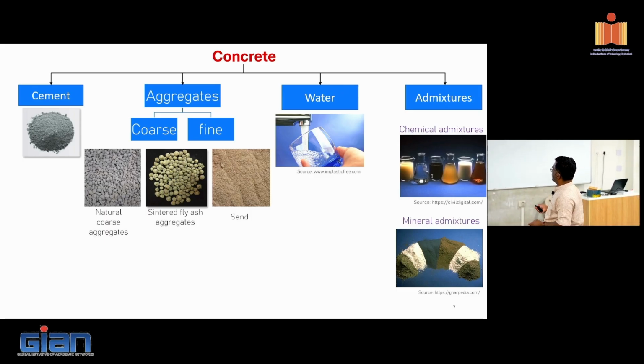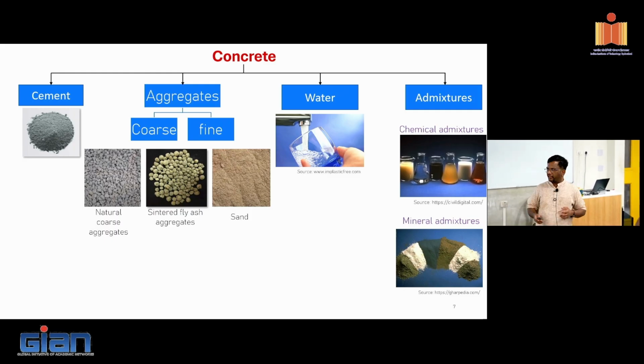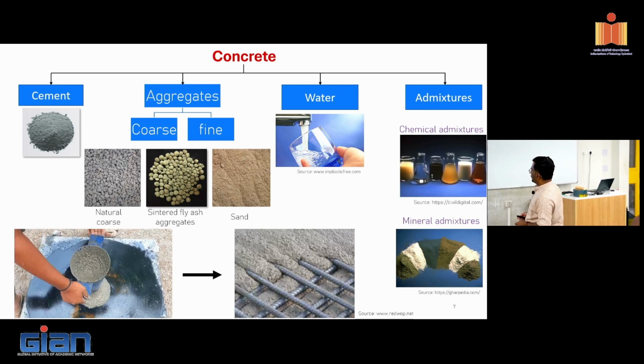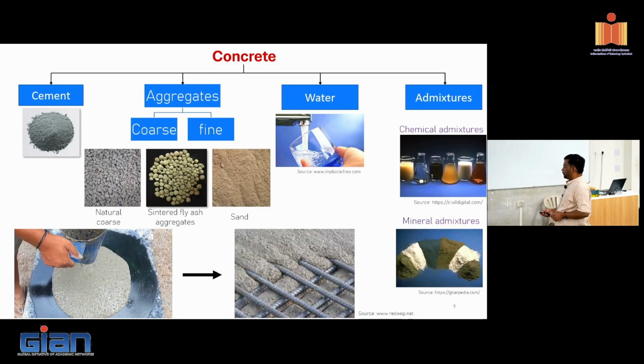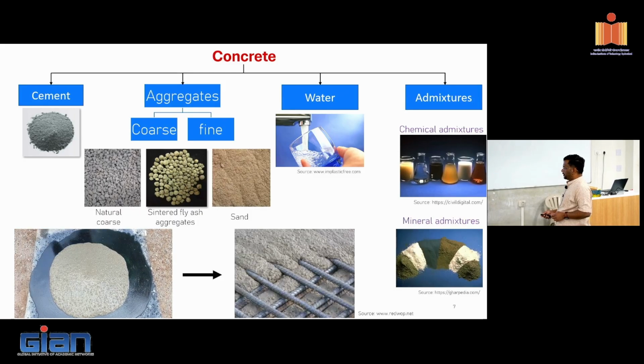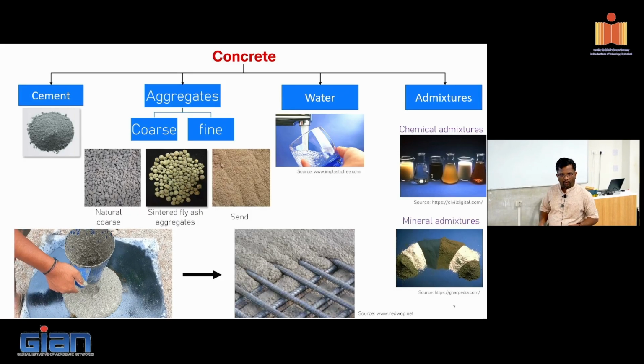In addition to that, I told you, chemical admixtures, there are so many products available. Similarly, mineral admixtures also we try to use so that you can tailor the concrete mix design according to the mechanical properties that you are actually looking at, right? So of course, for precasting or most applications, if you have heavy congestion of reinforcement, we need to have a flowable concrete.